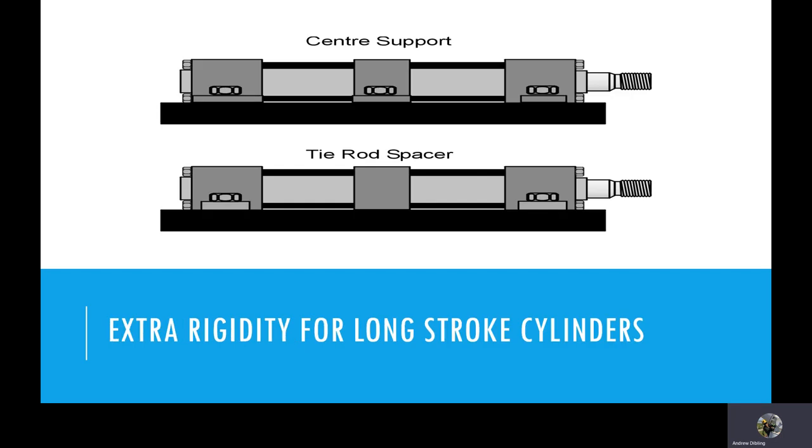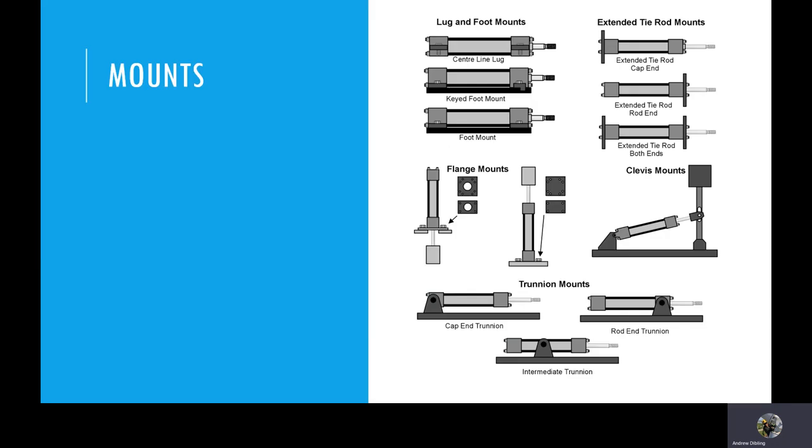So spacers, how to support my load. If I have a very large load, I might want to support it in more than one or two areas. I might want to support it in the center as well as on both ends, or I may need to space it for gaps. And that is used a lot on long stroke cylinders or telescopic rams, because we need that to be a linear motion over a long distance. And any deflection can result in damage to the actuator and leaks.